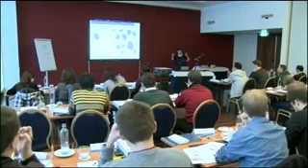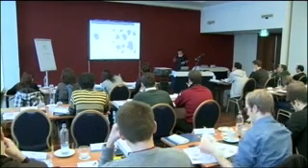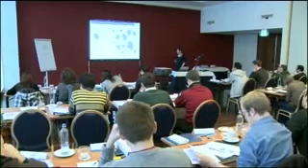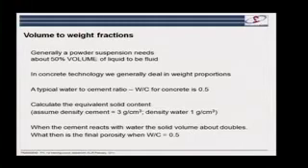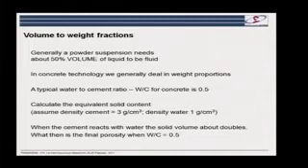Okay? And in fact, this has been known for a long time. This is the principle of the famous Roman roads, which, as you know, have existed even up to nowadays. They have this gradation of particles, and the idea that the small particles fill the gaps between the large ones. And then finally, we have to put enough water in to fill the spaces between the cement grains. Now, in order to have something fluid, we need at least 50% volume of the liquid.